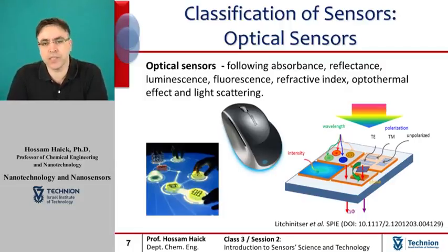Examples of proximity sensor usage include detecting an out-of-paper condition in a printer, or a mobile phone screen that dims to save battery life when placed near a face. The second subcategory of the optical sensors is called ambient light sensors, which provide precise light detection for a wide range of ambient brightness and are commonly used in LCD backlight control in mobile phones, LCD TVs or panels, and notebook applications.